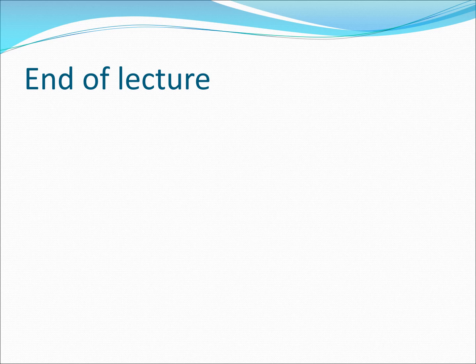So that was the lecture for today, where I introduced the very important concept of principal stress, and you clearly saw that principal stress is something which comes directly from the stress matrix. It is nothing but the eigenvalues of the stress matrix. And also we saw that the principal directions are the eigenvectors of the stress matrix, and the principal stresses are very important in various failure criteria, which I will probably discuss next, but maybe I will make a lecture on plane stress and plane strain before I move to that failure criteria chapter.